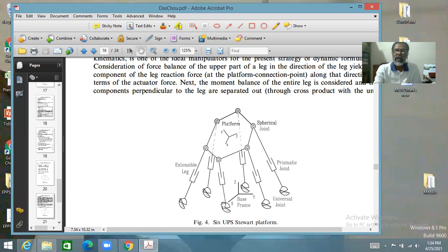And it is this which is actuated. So that means in every leg, one joint is actuated and the other joints are passive. So the six actuations which are in your control are connected in parallel. That is why it is called a parallel manipulator, and other parallel manipulators also share this trait with this.